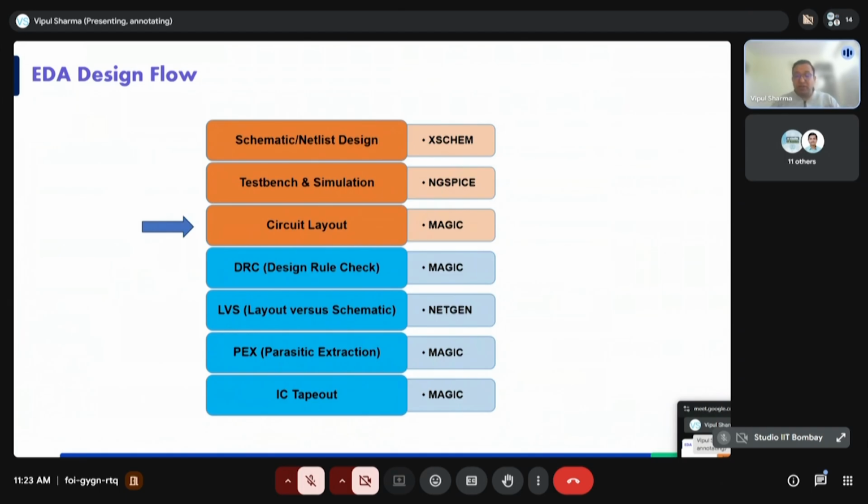So this particular technology has, I think, one local interconnect and five metal layers. So in total, there are six metallization layers available for you to make the connections. The lowest one is called local interconnect, and the other layers are called metal 1, metal 2, metal 3, metal 4, metal 5. And these are the layers. And then in order to make the connection between them, there are vias available.